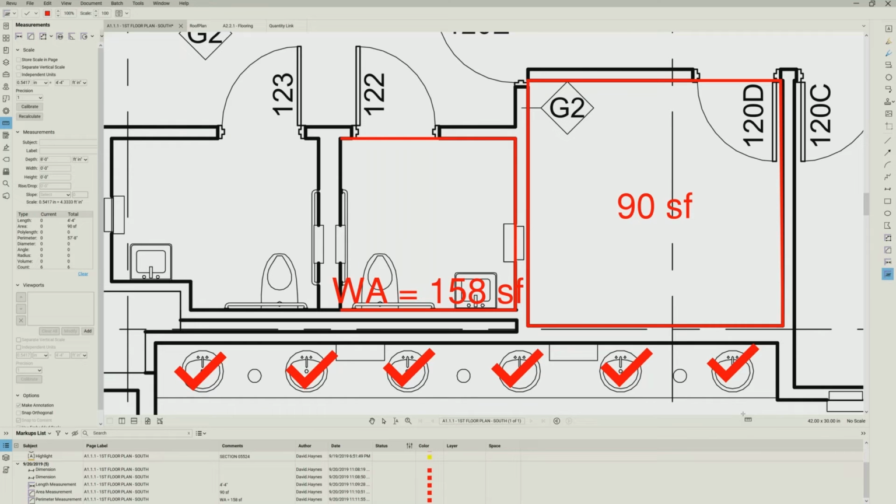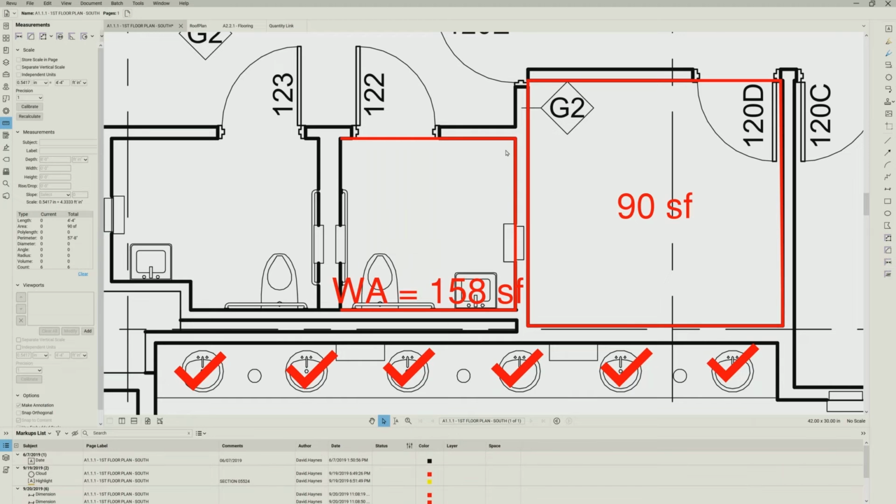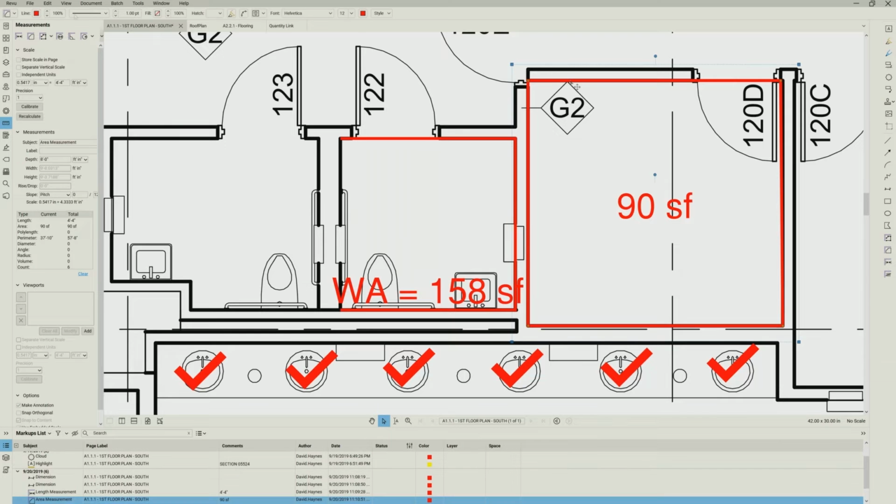All right, so now these all look kind of the same. And so I'm going to want to modify them first. Then I'm going to show you how to use layers. So first we're going to deal with modification, which is just the dynamic property toolbar. And for those of you familiar, this will be a redo. For others, it may be the first time you've seen it. So what I'm able to do when I select, such as this area, the property toolbar is dynamic, meaning it understands what I was trying to do and gives me what I would like to modify in most, but not all the cases. There's a few things that still hide in the property toolbar.